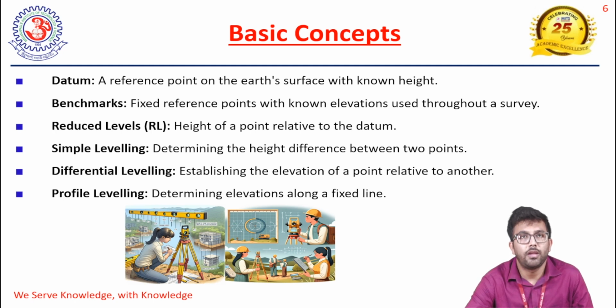Suppose we need to construct a house, as I gave the example, we would mark the location of the columns. If the ground is not an even surface, then we have to mark the elevation of the columns with respect to the benchmark, and for that we will design the height of the columns, and also the reinforcement in the columns based on the total area of the column that we are taking.